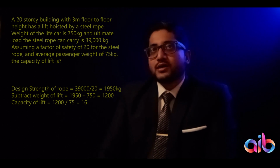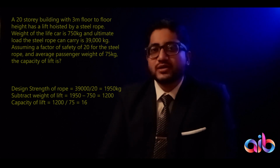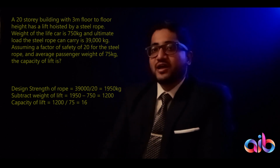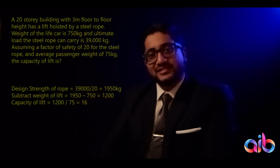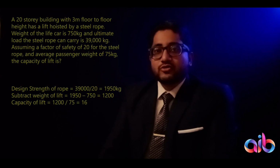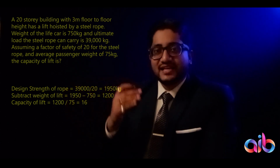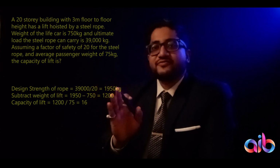So it should come to be around 40,000 divided by 20, so something slightly less than 2,000 kgs. So the load that you can assume for this sum, after having divided the ultimate strength of the steel cable, which is 39,000 kgs, by the factor of safety of 20, turns out to be 1950 kilos. So you would design the lift for X number of people such that X number of people add up to a total of 1950 kilos.